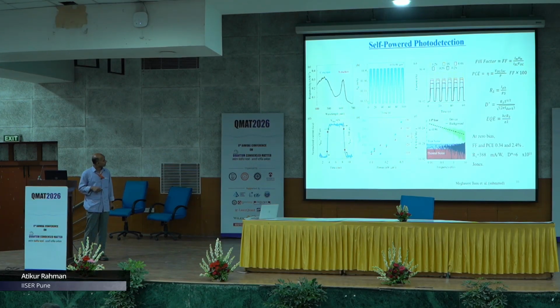And we also characterized their noise performance, which also looks a bit promising. These are the parameters that we observe: the responsivity is a few hundred milliampere per watt, and detectivity in the range of 10 to the power 11. We also back calculated the detectivity from the noise figure, which also comes in the same range.